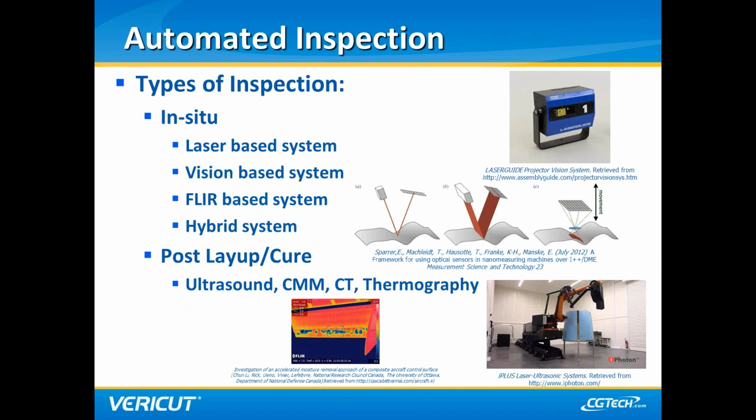Just quickly looking at some of the techniques, and this isn't all-inclusive, but just pointing out a couple. For those in situ inspections, you could have laser-based systems, vision-based systems, forward-looking infrared systems, or hybrid systems, which could be a combination of any or all of the above or others. And then post-layup, which is not extremely important for what we're talking about here, that would be ultrasound or CMM, some type of X-ray technology, CT for instance, or thermography.